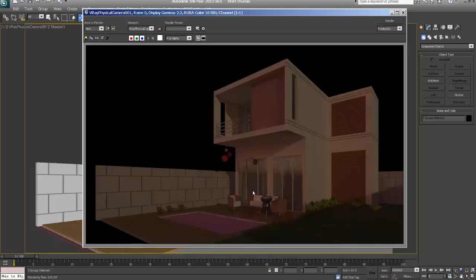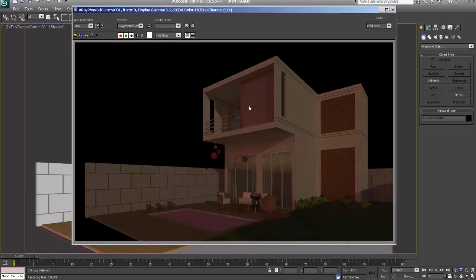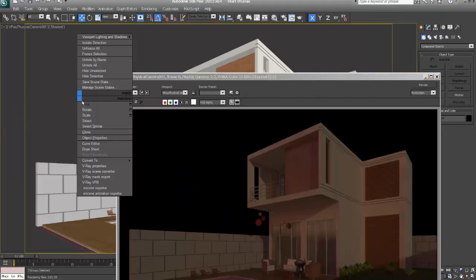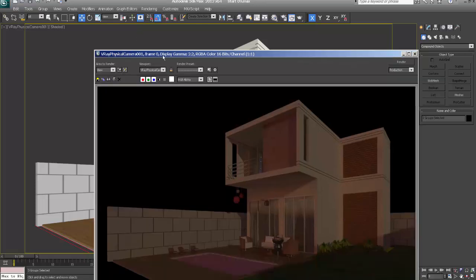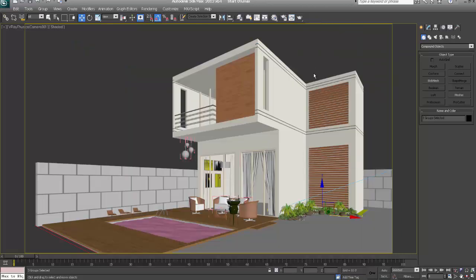So this is what I got with the rendering, and of course it has some reflections on the glass of the window panes, and of course I'm not so satisfied with the results, because we want a white and not so warm look. So I'll just bring down the sun turbidity, see how it happens, and decrease the intensity of the sky. So I'll just make those changes.